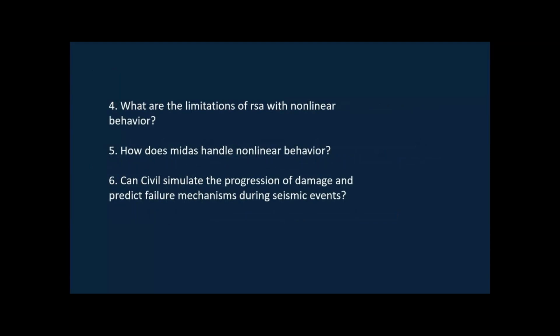Coming to the fourth question, what are the limitations of RSA with nonlinear behavior? RSA itself is a linear analysis. It is not a nonlinear analysis. So the limitations will be, as we saw earlier, the actual performance or the actual displacements of the structure will not be predicted by the RSA.